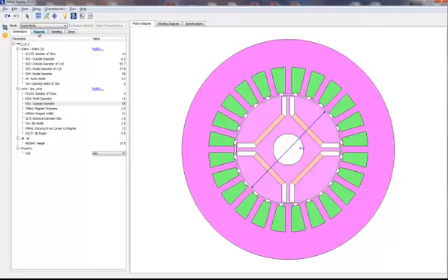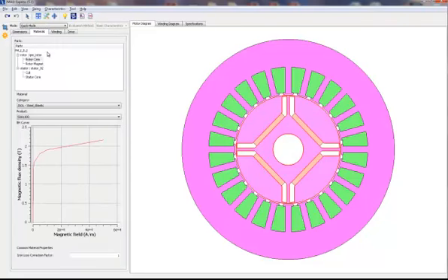We've set the dimensions. Next, we can move to the materials. In the materials tab, we can choose the rotor core, rotor magnet, and stator core. In an induction machine, we would get to choose the cage materials. In a switch reluctance machine, we wouldn't have the choice of a magnet. So again, the material properties, or whatever the materials used, are based on the type of machine analysis that you're working with.